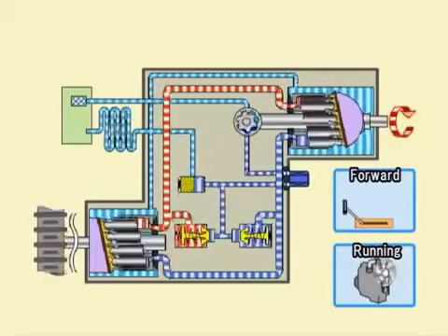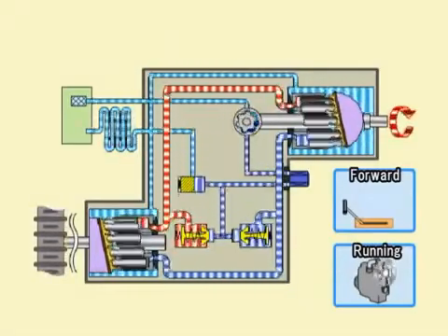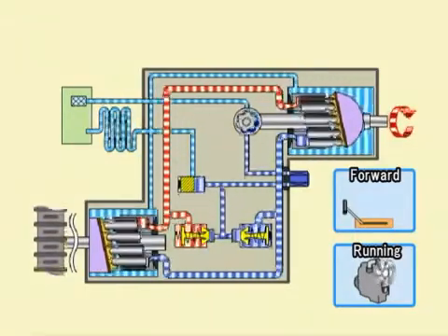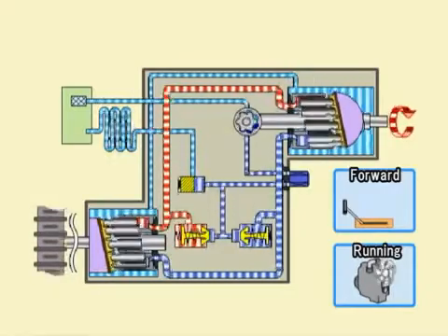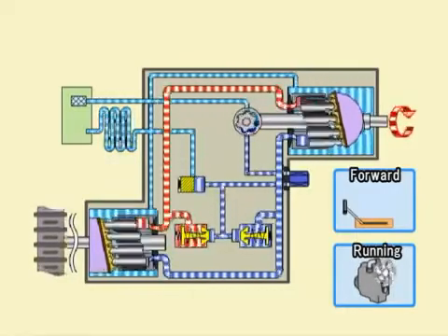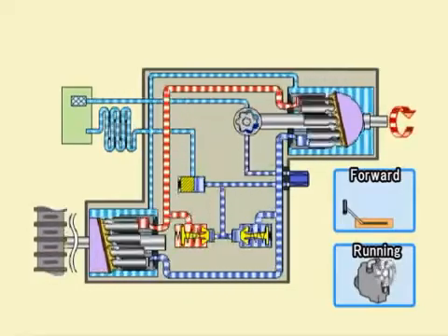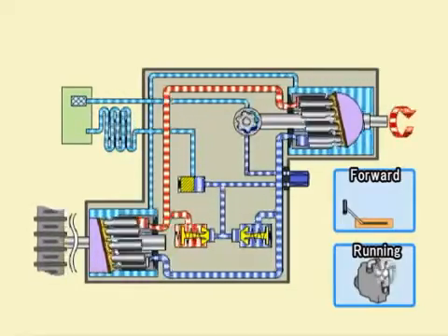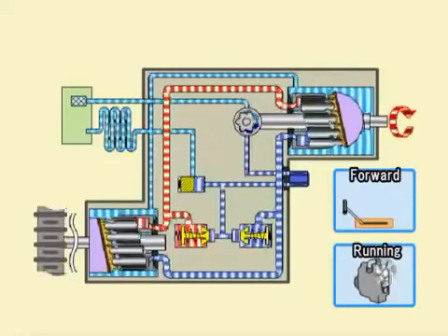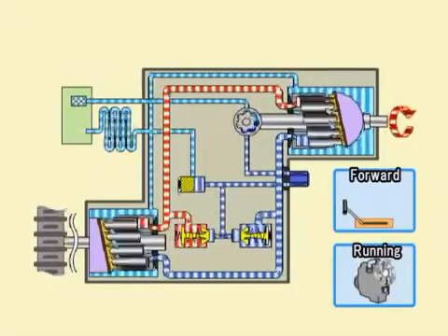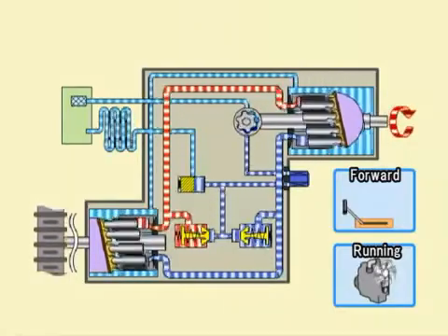The oil pressure in the high pressure circuit changes according to the output shaft torque. This means, for instance, that when climbing a slope at low speed, the oil pressure in the high pressure circuit will become higher compared to when traveling at the same speed on a flat or downward slope. When traveling on bad road conditions, the oil pressure is constantly changing. For explanation purposes, let's think that the machine is running smoothly with no obstacles.